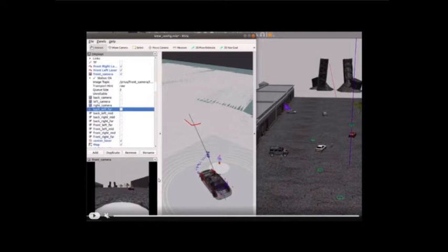This was done in the navigation stack, not in Autoware Auto. The previous 3 I have done simulations using Autoware Auto, and this one the navigation stack. And the ultrasonic sensors use the trilateration method, a mathematical model that is used to determine where the obstacle is.